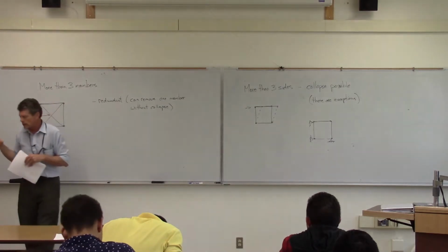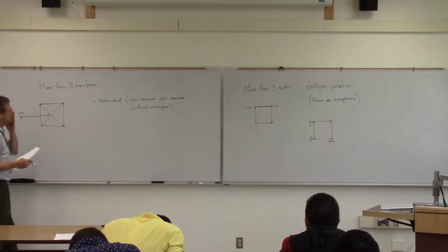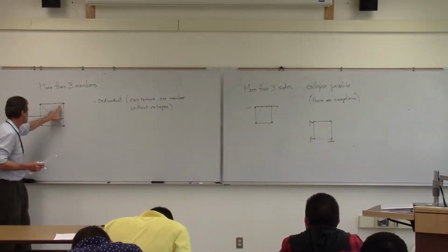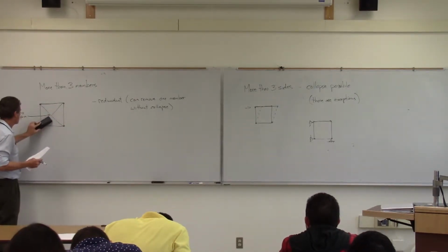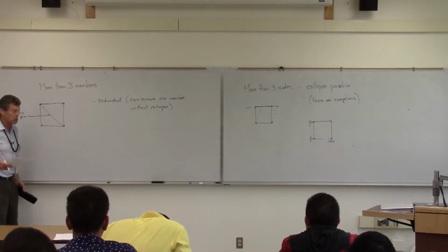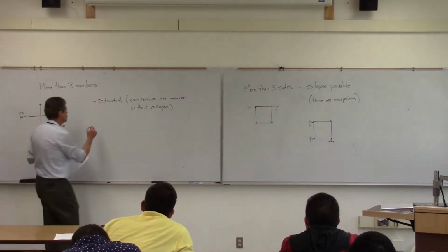the nice thing about redundant members, or redundant trusses, is that if one of the members fails, if just somebody cuts it or something like that, basically what we'll find is that it doesn't collapse. If this one disappears, like so, well, what we've got is simply 2 triangles hung together there, and away they go. They're fine.